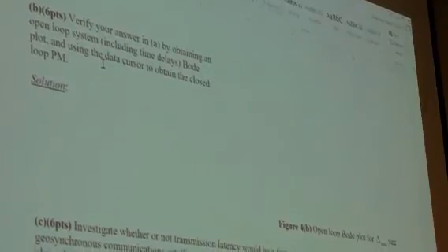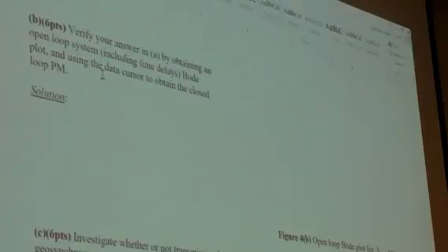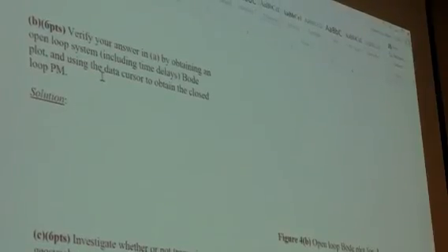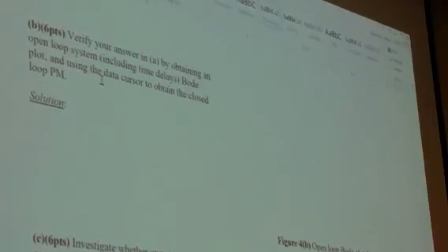You've just satisfied both of the root locus criteria, the magnitude and the angle criteria, which means that j omega is a root of the closed loop, which means the closed loop is marginally stable because you have a root on the imaginary axis. Remember, the whole idea of phase and gain margin gets back to the root locus, right?